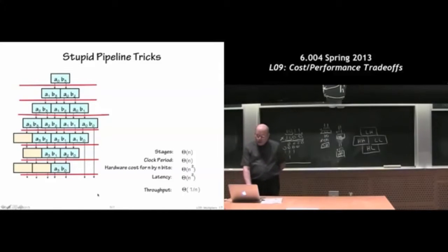So we have basically order n TPD in the worst case, for the row that takes the longest time. So that means that the clock period is order n. We still have n squared hardware. Think of this as really just adding 2 registers to each of these blocks, or just registers on these two output bits. And so that means I've gone from a hardware cost of 2 full adders and an AND gate.